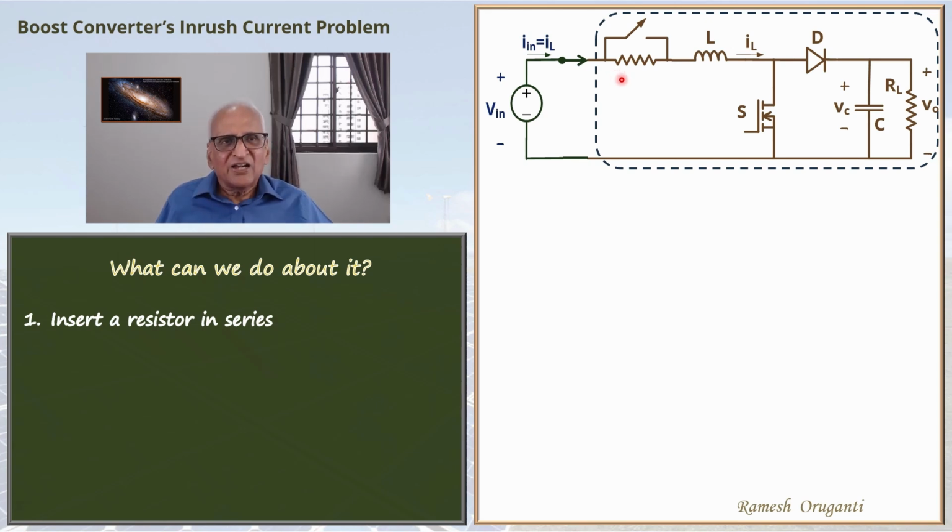If you put a large value of resistance so that it will reduce the current sufficiently, then the capacitor won't get charged to the full value of 180 volts, but a reduced value, maybe 80 volts. Now if I close the switch, I will have another transient as the capacitor gets charged from 80 to 180 volts. Designing this may be a bit tricky.